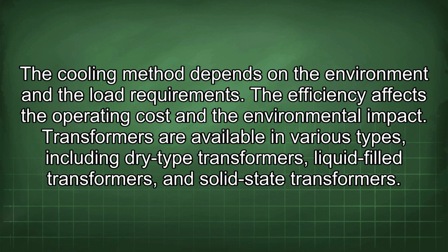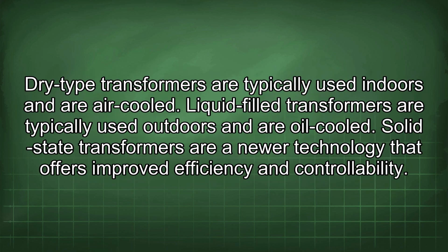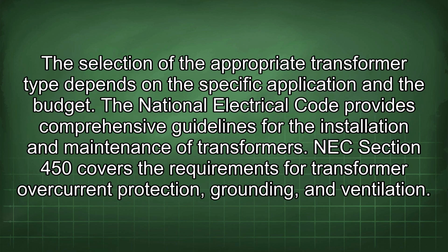Transformers are available in various types, including dry-type transformers, liquid-filled transformers, and solid-state transformers. Dry-type transformers are typically used indoors and are air-cooled. Liquid-filled transformers are typically used outdoors and are oil-cooled. Solid-state transformers are a newer technology that offers improved efficiency and controllability. The selection of the appropriate transformer type depends on the specific application and the budget.